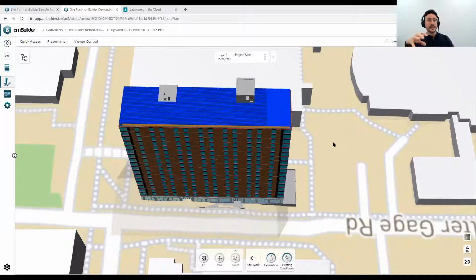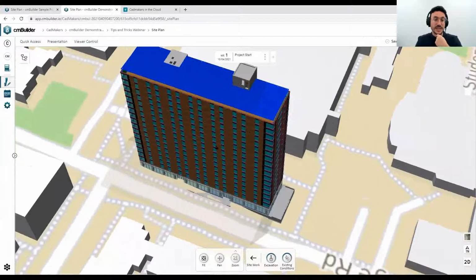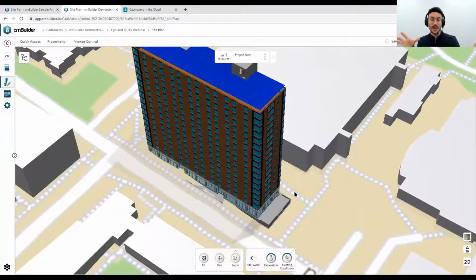Yeah, for now, this is what you do. But what I like to do is to create some reference marks that allows me to have some global references. So for example, let's say that you were working with this 3D model and you're going to bring in something that is, let's say, a mechanical model that is inside the building, right?